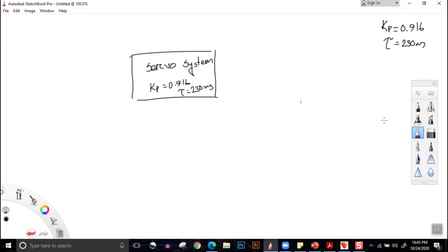Now, we have been measuring the velocities till now. We have only worked with velocities, and now another thing that we need to consider is position. Till now we had input as voltage, output as velocity, which has been converted to voltage by the tachometer. So now we know that V is equal to ds/dt. So in order to get distance or the position from velocity, what do we need to do? Obviously, we need to integrate.